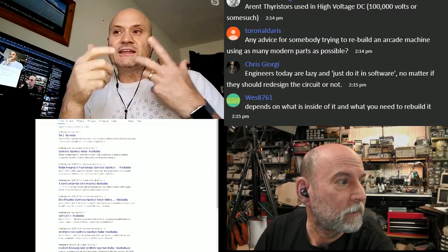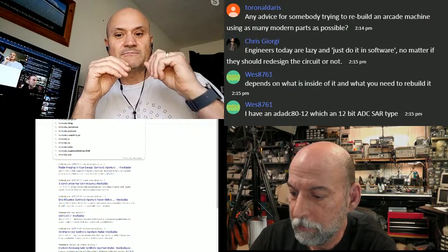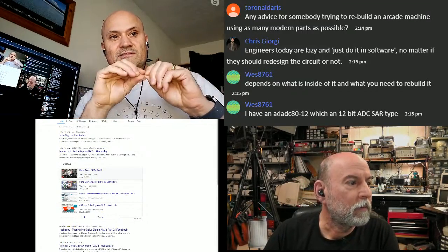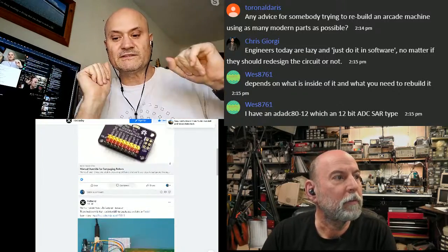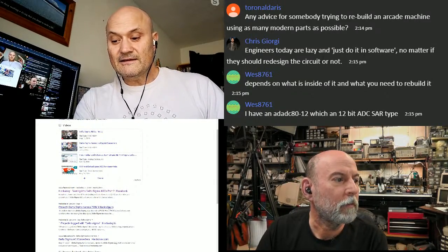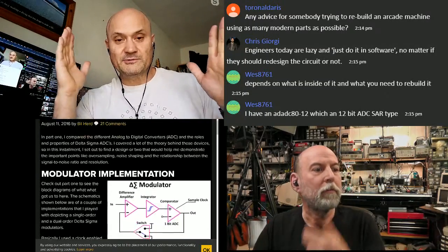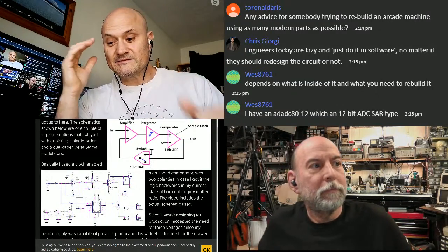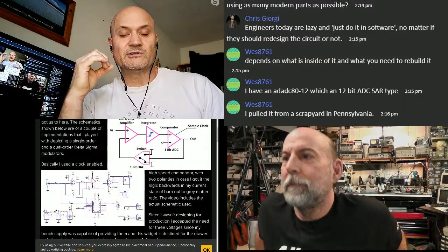So yes, in a sense, it was 1-bit in that it had the high-low output of the comparator, but digitally it would be shifting that into the successive approximation shift register, and that would give you the full 12 bits. But to get high-quality audio, and these things are amazing, they actually have full 20 hertz to 20 kilohertz bandwidth, and over 90 dB dynamic range, which is impossible to do in 12 bits mathematically.